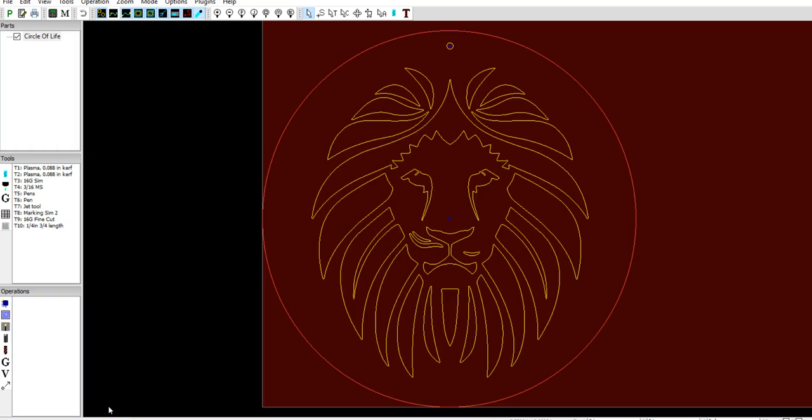Good morning. Today we're going to talk a little bit about kerf width. We're going to make some adjustments to showcase differences in kerf width in order to not lose specific small pieces that we may have thought were going to be retained when we were initially cutting, but end up being burnt out because of some of the overburn that occurs when working with plasma. And we can compensate for that here in SheetCam.